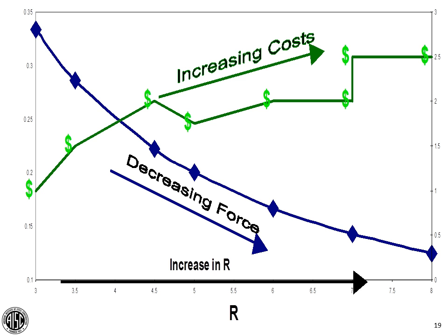Now, the idea that these seismic requirements have some cost associated with them is sort of reflected in this graph. This is kind of an informal graph. I wouldn't read too much into it. But the basis of this graph was that there was an engineer in the Northeast who wanted to see what the cost impacts were for various seismic systems. And so he took a building and he designed it using various systems, brace frames, moment frames, R=3 systems that weren't specifically detailed for seismic resistance, and then he put them out to bid with a handful of fabricators to see what the differences in costs were and kind of distilled all that information.